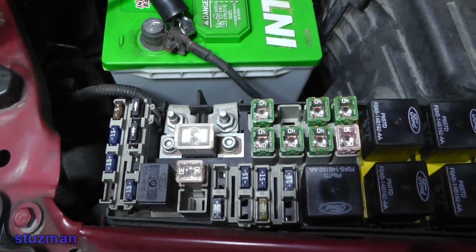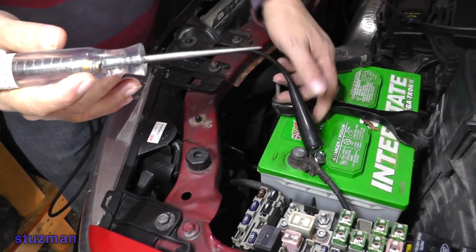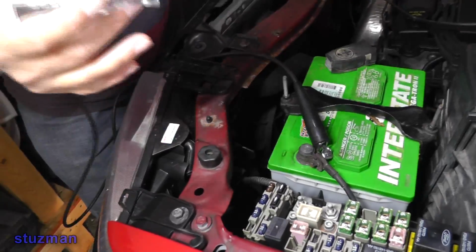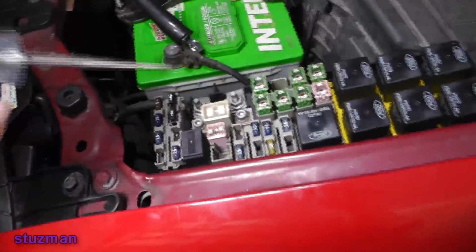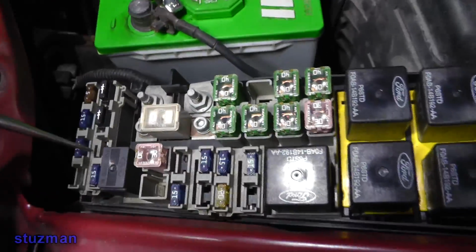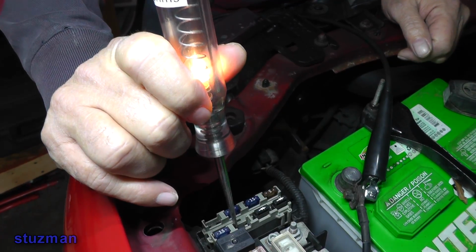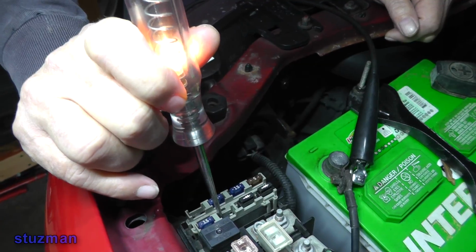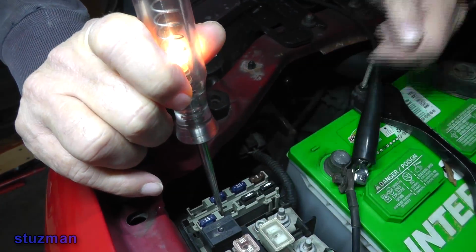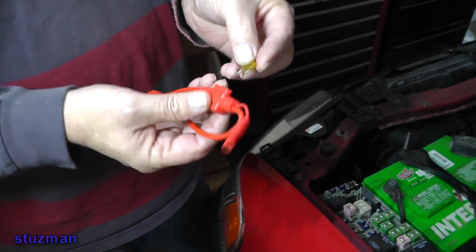Now I have my test light. I've got it hooked up to DC negative on the battery. Okay. This is not necessary, but I'm just illustrating my next thing about amp clamps. Now if you remember, this fuse was hot all the time. So I want to see which side is hot. And I can see it's this side over on the right. Okay? And of course if I go over here, there's nothing. It's hot over here on the right hand side. This direction.